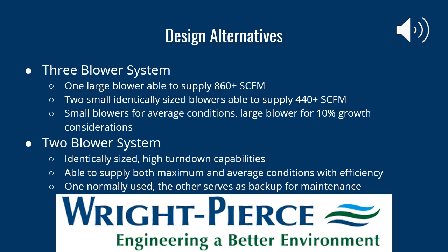The 2 blower system would consist of 2 identical blowers that would have turn down capacities to operate efficiently for all air requirement conditions. The redundancy of blowers is required for instances where the main blowers would need maintenance.